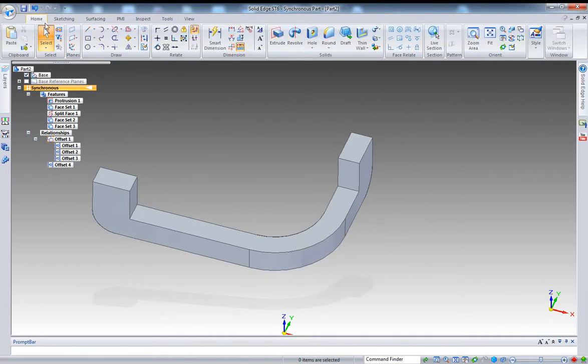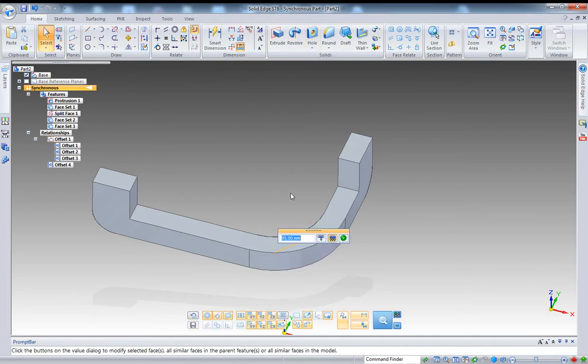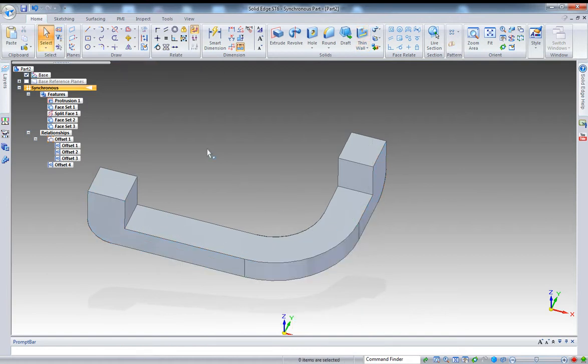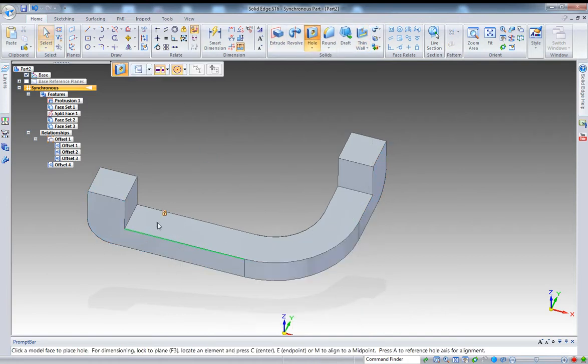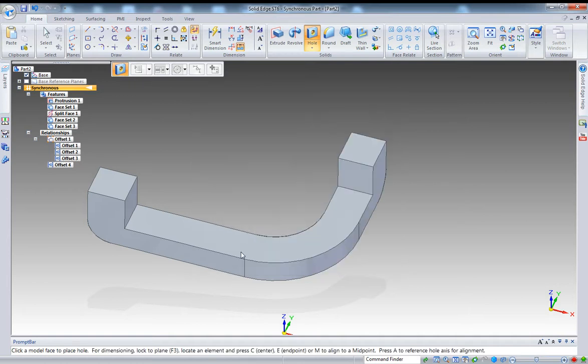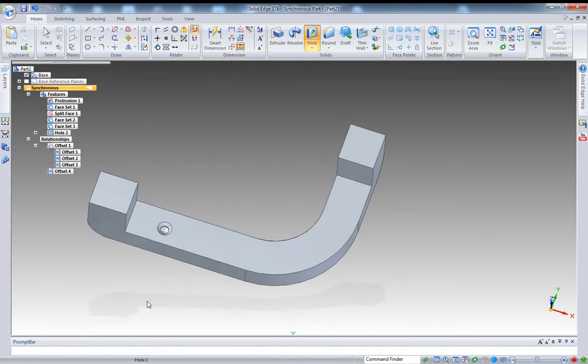What else do I need to do? Oh yes, holes. So if you go to holes, probably if I want to keep that offset here, like this, want to drill a hole on probably something like counterbore hole, countersink, because I think countersink was what was in the video. Let's go with 1.5 and 2.5 for this one. I think it should be good. Yep. So place it here.